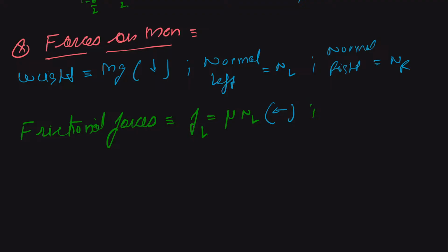And then we will have FR, which will be mu times NR. Its direction will be also the same, and these frictional forces are going to provide the necessary centripetal force.